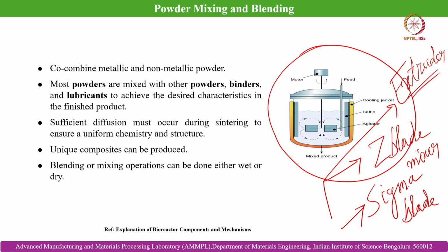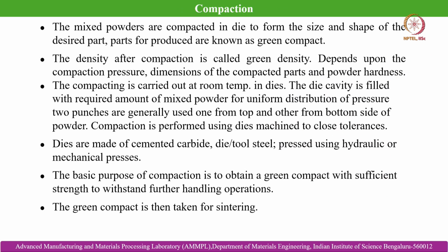This powder additive or binder mixture is mostly carried out in wet state, where the additive undergoes a phase transformation from solid to liquid, which also facilitates it acting as a binder to mix the solid powders.